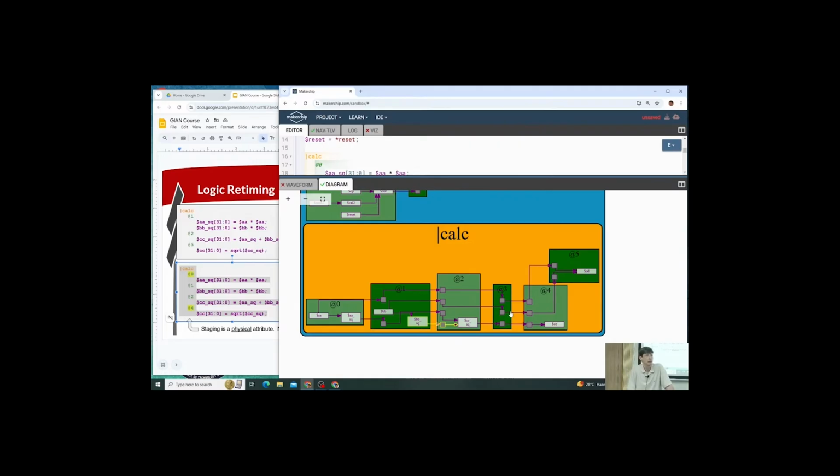Right. Yeah, the pipe signal is going to exist in every stage it's needed, so from the time that it's assigned to the latest use of the signal. And you can also use sub-ranges of a signal, right? If I only used bit 0 of the 31-bit signal in stage 1,000, just that one bit would get staged off to stage 1,000.